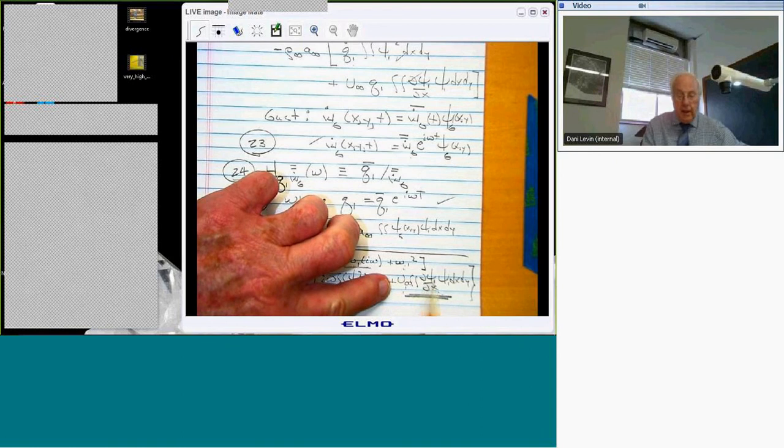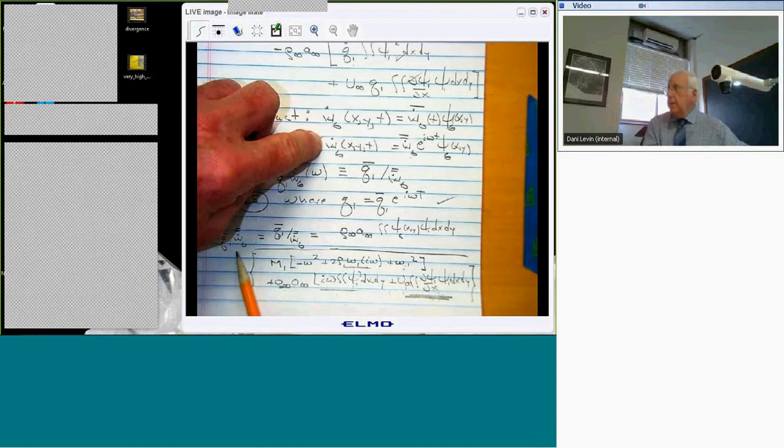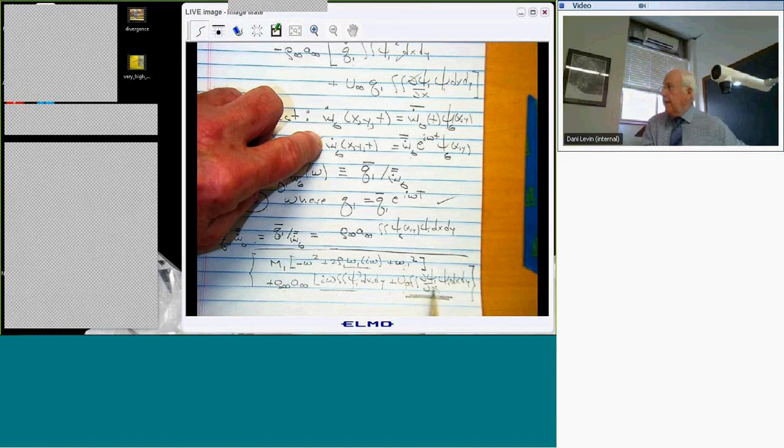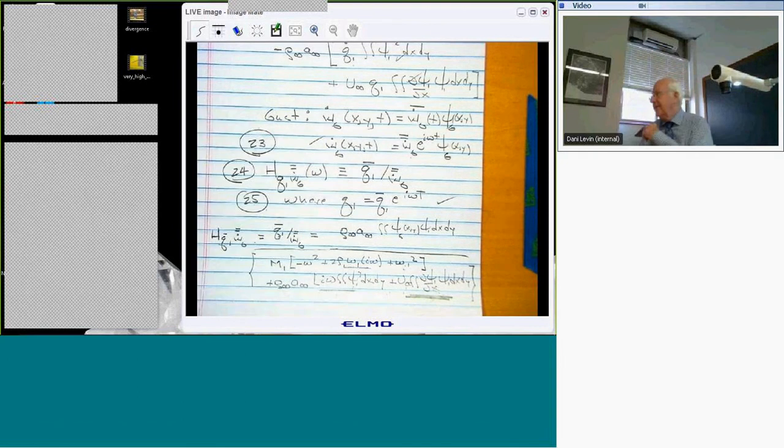And right at the divergence condition, how big is the transfer function? When these two terms cancel, how big is the transfer function? Very big. Yeah, right. It's real big. It just has to have a huge response. Well, the point is, if you do a gust analysis and you do it carefully, and you really are going to encounter divergence or even flutter, the transfer function will go to infinity at that condition. So the response, therefore, will go to infinity, and you'll see it, right?